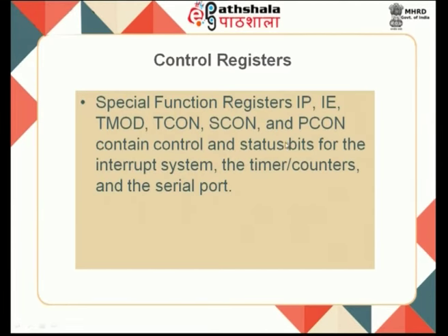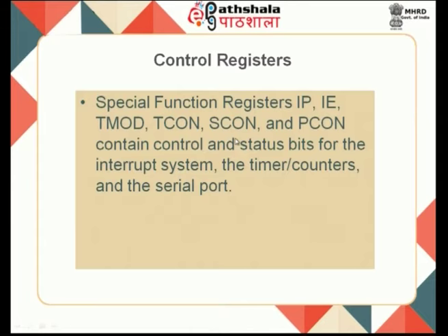Here, the interrupt enable is used for interrupt handling, TMOD is for timer control, and TCON will facilitate your timer mode as well as serial communication and your IE, all those things combined together to hold it, and SCON is meant for your serial communication register.